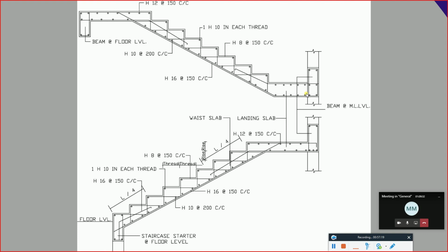We are going to have the bending moment going up here, and then bottom, and once again going up. Now if I shift this one up a little bit as a regular stair, it means that there is a bending moment going up at this particular support, and then it goes bottom for the span, and then once again it goes top for the support. So for ease of use for the staircase, make it straight.